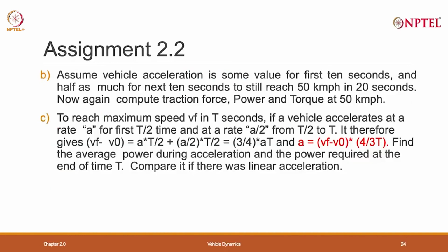Another problem, assume vehicle acceleration is some value in the first 10 seconds and half as much over the next 10 seconds to still reach 50 kilometer per hour in 20 seconds. Now, again compute the traction force, power and torque, and this problem, number C, is what you need to do before B, because this will give you the kind of expression that you will require to compute that.